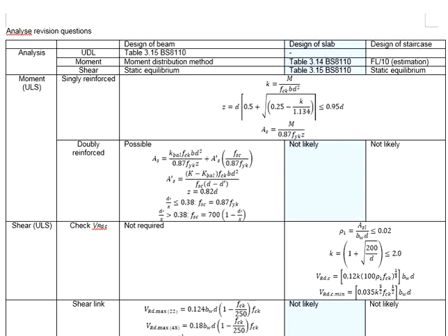The compression resistance of the member is normally more than enough to cater for the compression stress generated due to the bending moment acting onto the member, and therefore you do not require further strengthening of the concrete with the compression steel bar.